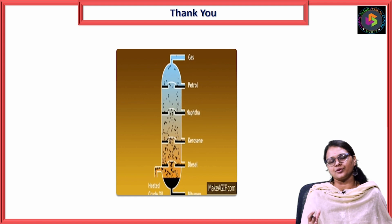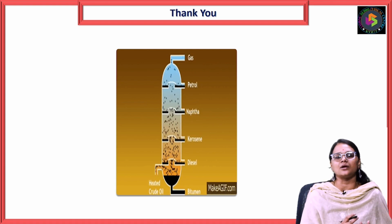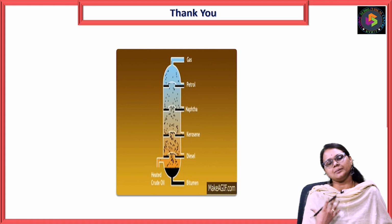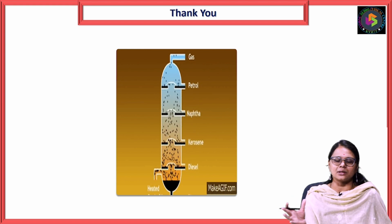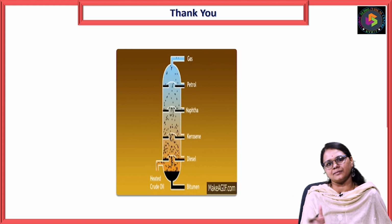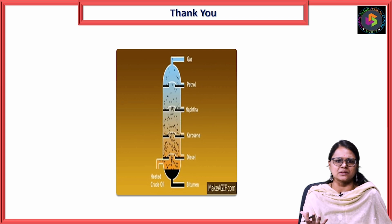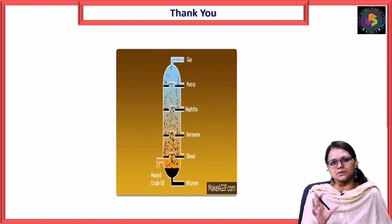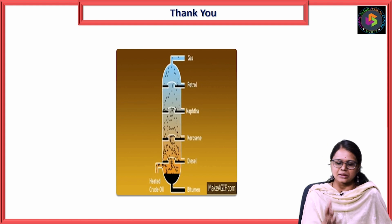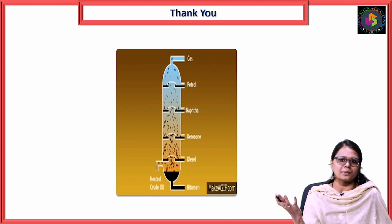Based on that, you can get to know whether to go with distillation to separate a given unknown sample. For a known sample, all the data is available, so it's easy to run. Petroleum industries, for example, have huge data, so there won't be any changes. Depending on the crude oil properties, there will be some changes in the pre-treatment. But in a distillation column, if you maintain the temperature, you'll have that component separation.